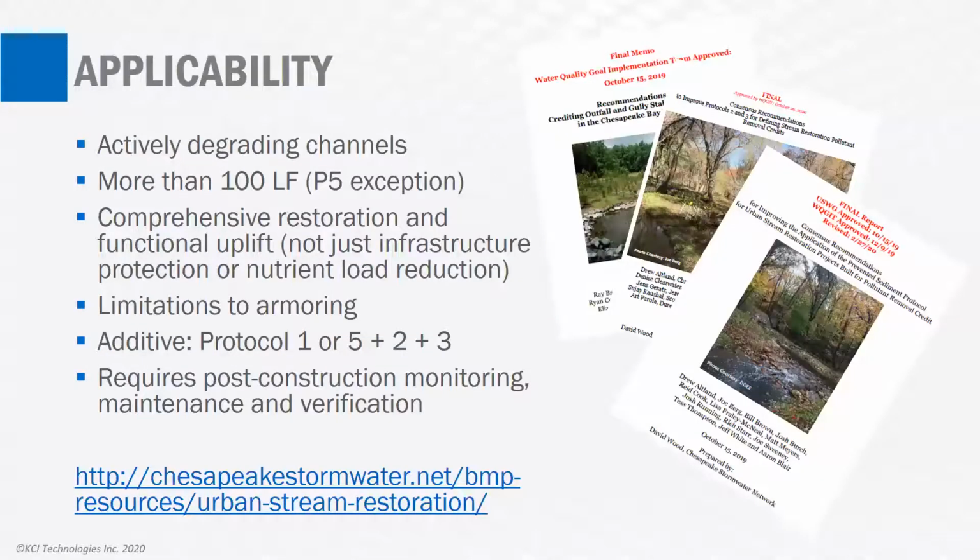To be eligible for credit, the restoration has to be for an actively degrading channel and restore more than 100 linear feet. It has to provide a comprehensive restoration and functional uplift. So you can't get credit if you are just out there patching up a local bank or stabilizing an exposed utility crossing or something like that. It has to have a more systemic approach to the restoration. The new guidance does identify limitations to armoring, which Hannah's going to talk about in more detail.